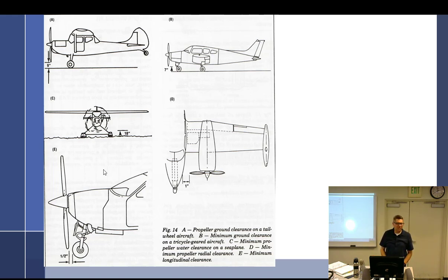Or if I said, a couple nicks, dings, scratches, I don't want to do it, I think I'm just going to send it to the prop shop. Okay, that's just routine maintenance. It may have been one ding too many for you. It's time to get some maintenance done. But if you bent it, smacked a tip, or have to shorten it, that's a prop strike.